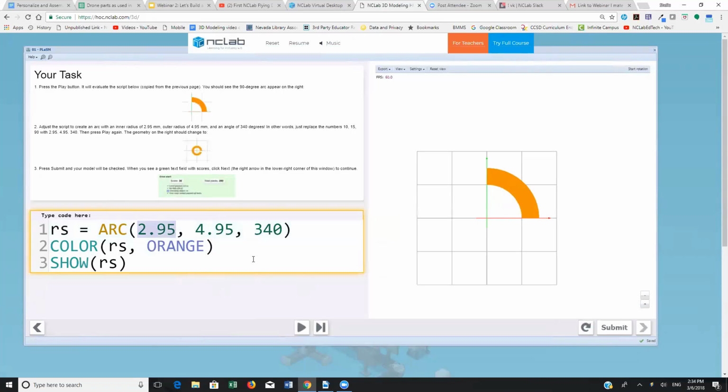What we've found is that, if you go to use your own 3D printer, some materials are not very precise when they print. And you may have to increase this number a little bit to make those motors go into that holder, into the socket. I experimented with some PLA and I ended up using a value of 3.15 and it worked.